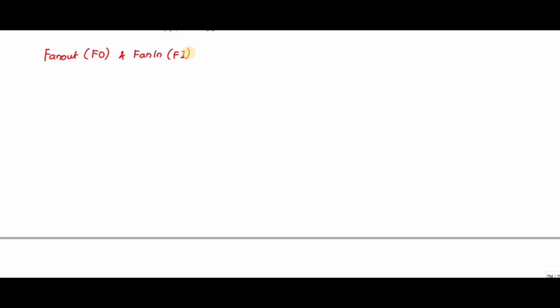So these are the factors that are defined, which are based on some current values, that correspond to the allowed input voltage, respectively, to guarantee the output voltage. I can write this fan out low, FOL, as IOL divided by IIL.